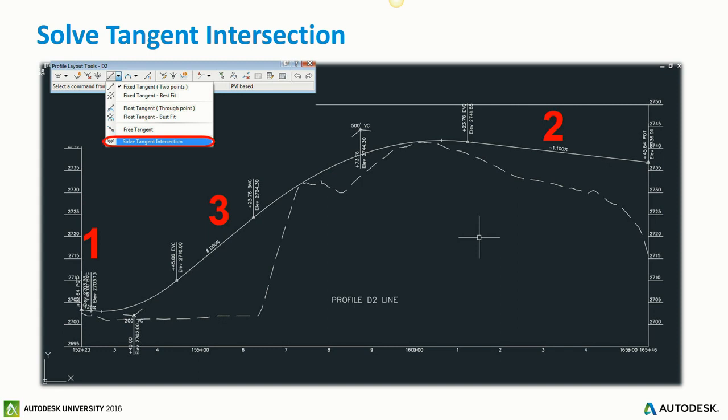So this is an existing street, so we know where it starts. We know where that tangent is, so we can get that point. And on the end, this ramp goes and meets an existing ramp over there, so we have to match up to its grade and know exactly what's the elevation of that. So what we know of that ramp, we'll use that. So we have an end constraint and we have a start constraint. Another constraint, the ramp can only go up 8%.